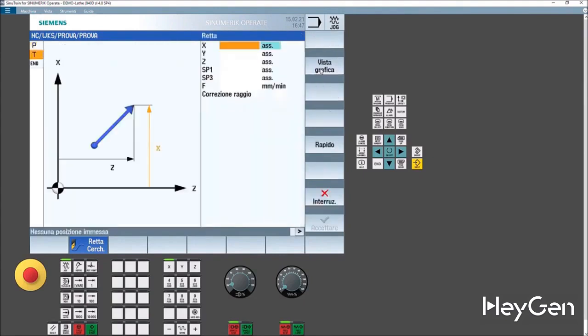Accept. Straight. Okay, we said I have a diameter of 100, so I'm going to 102. Here I have a doubt. I think it stops at 107 because we set a safety limit, but I think it only applies to fixed cycles. So, just to be safe, it might go up to 110. Then you'll learn to know your machine because it also depends on the parameters like X105, Z0, F0.3.